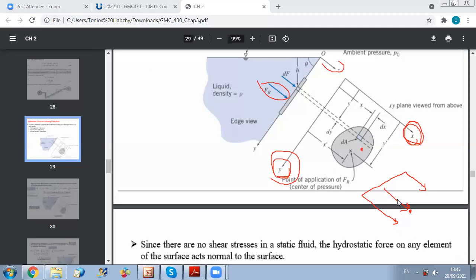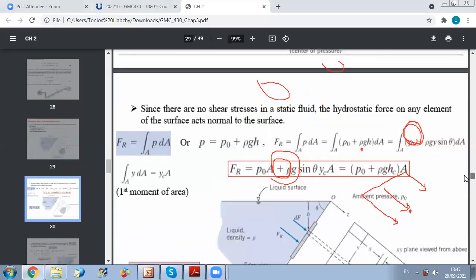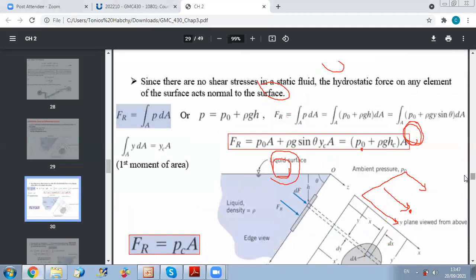And if you put, let's say here, the moment about Y axis is negative. When I want to put the condition of sum of moments, it will be a negative moment for the resultant force and a negative moment for the moment of the distributed load. So minus minus can be cancelled out. This is why you don't care a lot here for the sign of the moment.